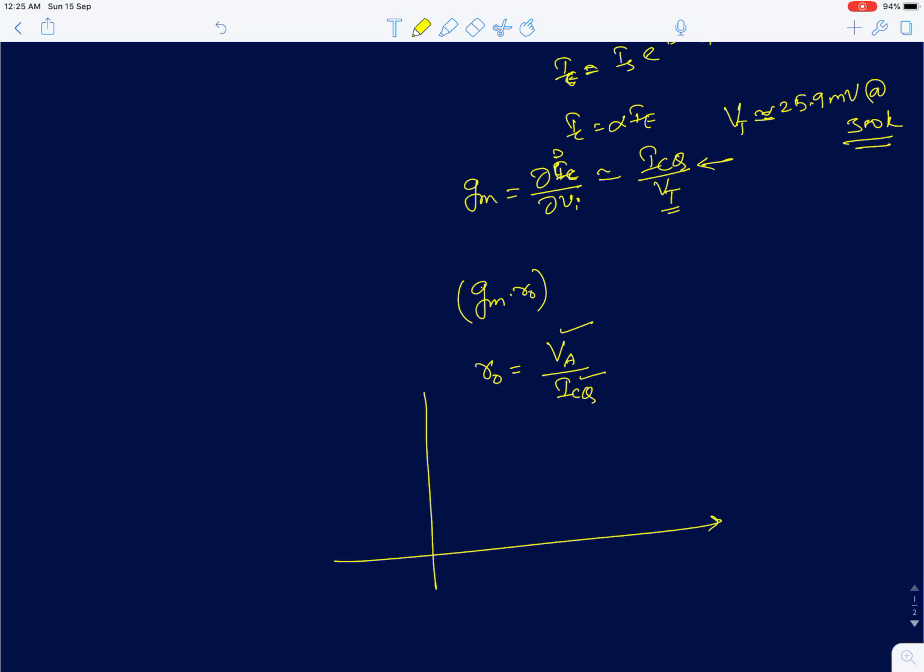Again, this is a very well known point: if I vary the collector emitter voltage VCE and plot the collector current for a given quiescent base emitter voltage, once the device is in the active region of operation the current is supposed to remain constant, but in reality it actually increases slightly. This is because of a phenomenon called base width modulation. Any standard devices textbook will tell you what it is.